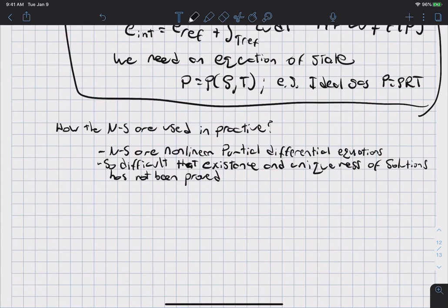Okay, and what I mean by this, and that's even in the arguably simpler incompressible case, where we're solving the divergence of the velocity equals 0, and rho dv/dt equals minus grad p plus mu del squared v, and that's even ignoring gravity and things like that. So just solving these equations here is extremely challenging.